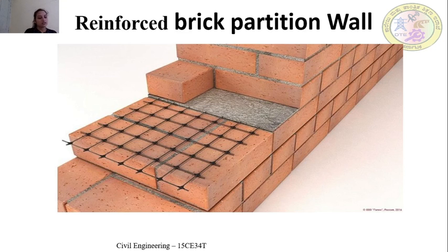So just now, like I said, the reinforced brick partition wall, the reinforcement here, the reinforcement of steel mesh strips will be provided after every 3 to 4 courses. So the reinforced brick partitions of half brick thickness are more durable and possess more strength.